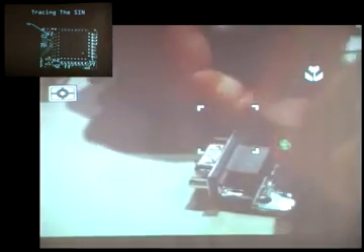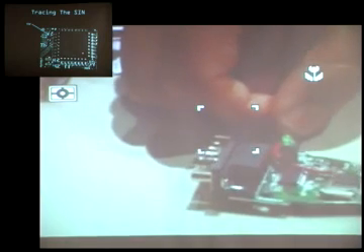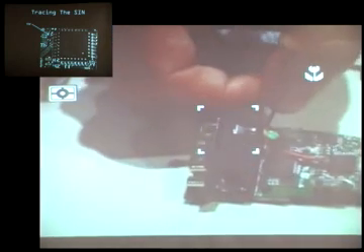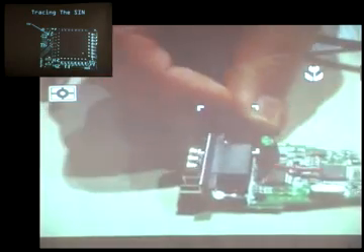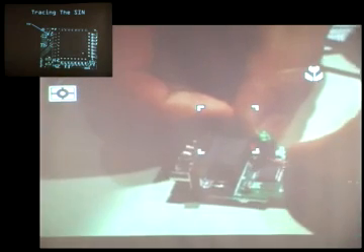Alright, so when you're tack soldering, see now I've sort of jigged it up. I've kind of bent it to the right size, so it's almost the right place right there. I'm actually using the board itself to try and hold it in place, because I don't want to have to hold it in place really while I'm doing the work. So that's one thing to sort of help you out while you're doing it. And what I'm going to do is I'm going to take this wire to pin 19, which is one of the signals of interest that we identified, right?